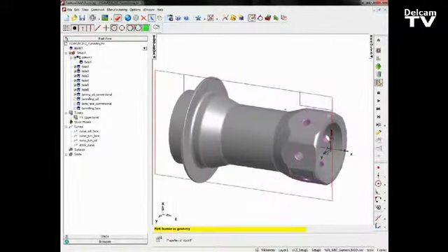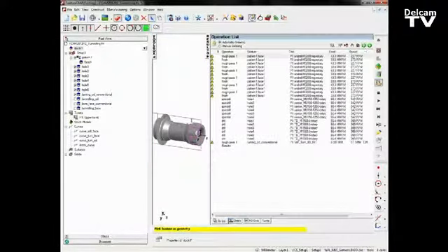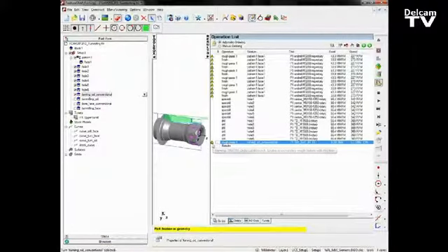So let's look at what we would do if we were conventionally turning. Here I've got the pattern of faces and then the whole operation. If I go to my results tab, I'm just going to turn a breakpoint on the rough pass. Note it does say that there is an undercut on this particular feature, and if I go up to these features here, it also says the tool diameter that we've chosen, which is a 32mm solid carbide tool. In this case, just looking at the curve, it detects a small radius in the curve, but we're not going to be too concerned with that.